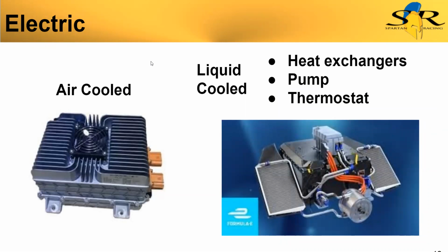For electric vehicles, electric components, as I said before, get hot. There are inefficiencies and waste heat. There is some air cooling similar to the regular engine, where there are just fins, but most electric vehicles and their components are now liquid cooled, because of their high performance nature. Controlling that cooling allows them to run more efficiently and optimally.